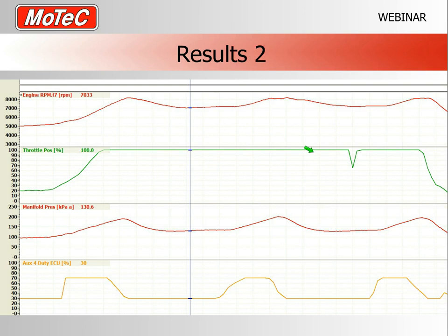Now that shows you how you've got to customize how quickly the system checks itself and calculates its different parameters for how the system responds. So if the system is a very quick responder, we need to use big, high P numbers to respond quickly. If the system responds slowly, then the proportional gain numbers, the P numbers, need to be slow as well. We can't have it calculating too quickly, otherwise it just keeps calculating on a system that hasn't responded yet.